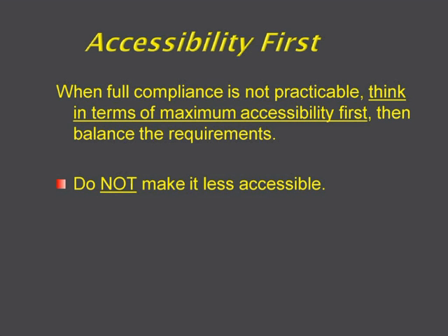You've got to think in terms of accessibility. Like I said, you've got to step back and look at the thing as a whole. Whatever you do, don't make it worse than it is. I've seen some cases where that's happened, with good intentions. There was one where we had a building close up tight to the right of way on a corner, and the ramp was steep, and the designer decided, well, I want a 5x5 landing, which shortened up the ramp and made it steeper. So you had a nice flat landing that no one would be able to make it up to because the ramp had gotten too steep. So don't make it worse than it already is.